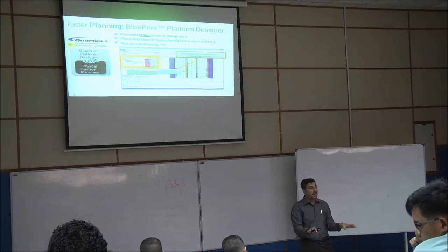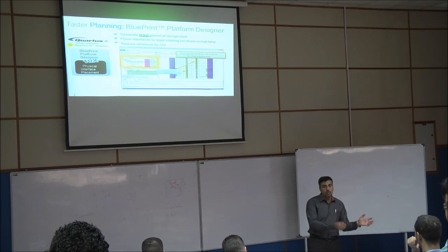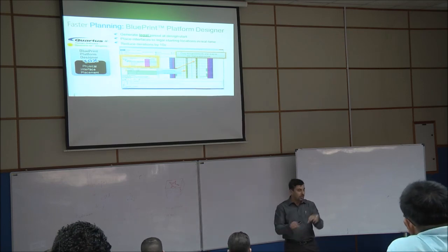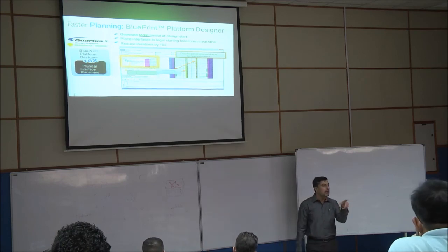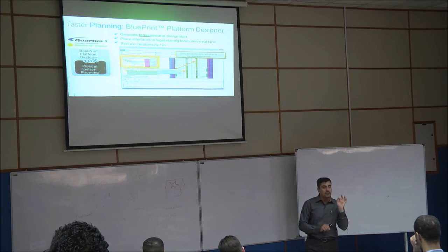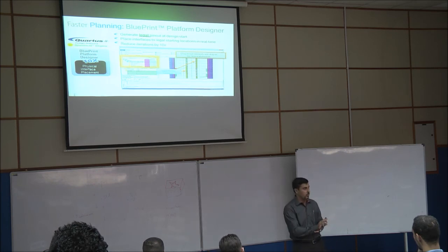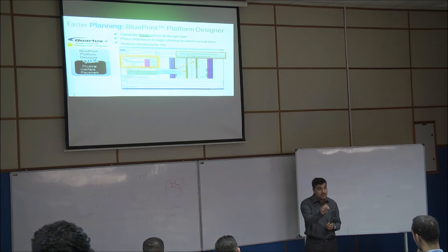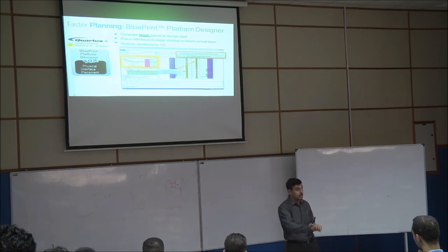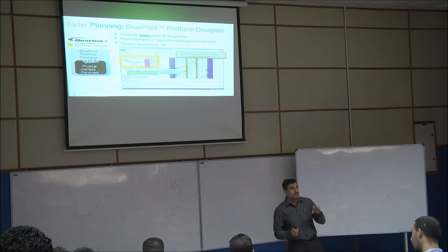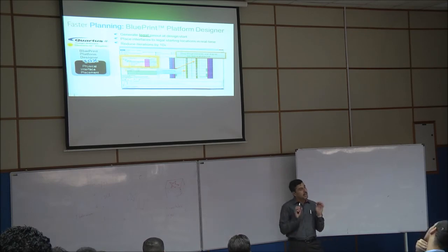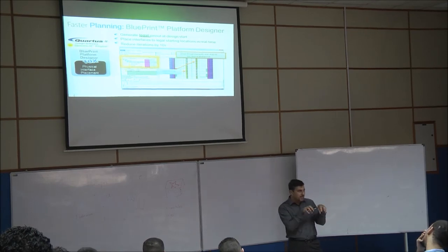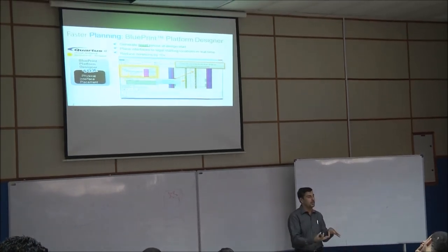We can arrange our design on the chip by ourselves. Now normally you do compile, right? So the compiler, the CAD tool, will arrange your design on the chip, right? Put this block here and this block here and so on, and do connection routing, right? This feature you can already do by yourself also, but it needs very professional knowledge from you, because the compiler chooses the best according to the algorithm already implemented in the CAD tool. But sometimes, as a designer, we have our sense.